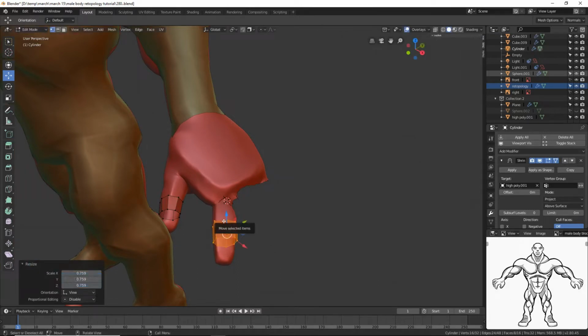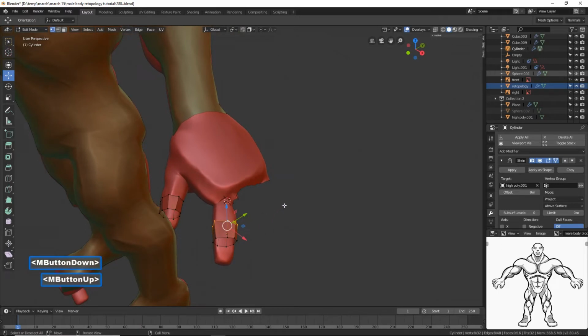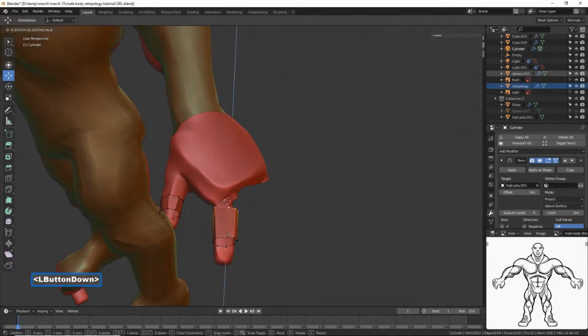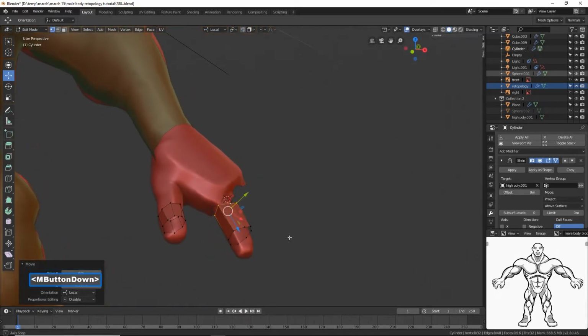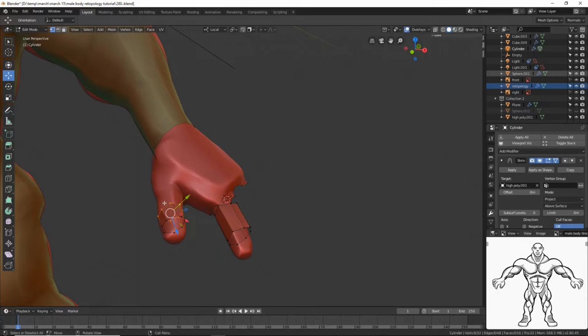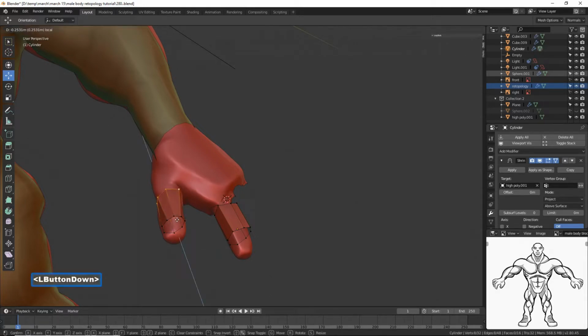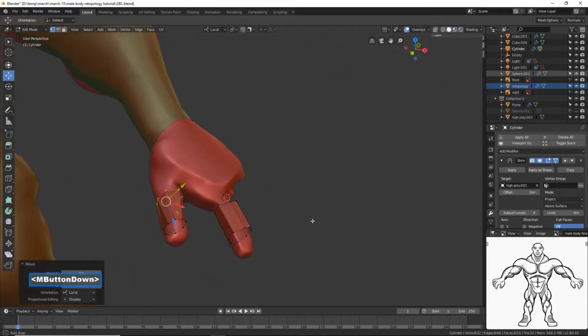So what I'm going to do is left click, hold Alt, click here. This manipulator, see where this says global? We'll click here, we'll change this to local. And that lets us have a little more control. I'm going to hold Alt. When I held Alt and selected here, we're on vertex select, I was able to grab the ring of vertices there.